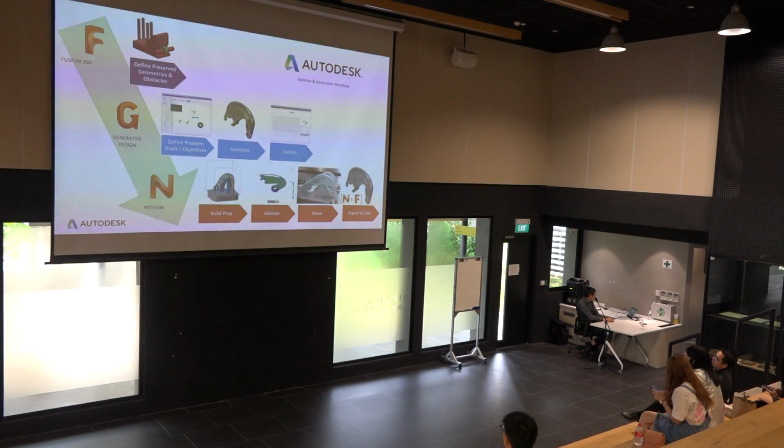We have these tools already merged together right now, and then we have another one which is Netfabb, because Netfabb will involve the lattices, the lattice structures inside the model. And you're talking about how you're going to optimize it, and at the same time, when you do printing, you want to eliminate unnecessary warpage due to heat, right, it will warp. So this is the complete workflow. Towards the end, you need to export it into CAD. And then maybe in the CAD itself, like what I showed you earlier on, you need to refine it by dragging it and changing the shape and all this.